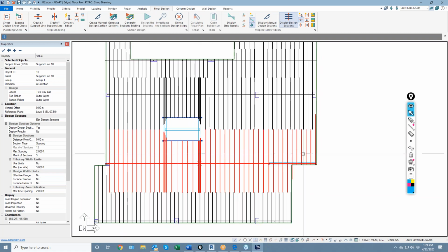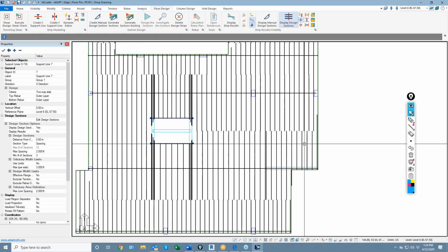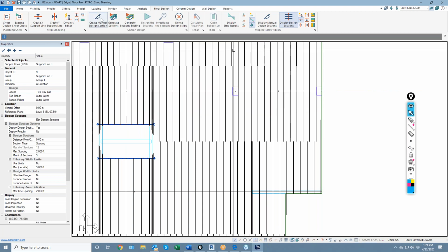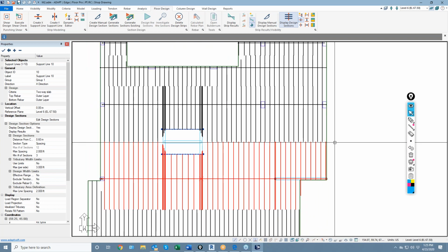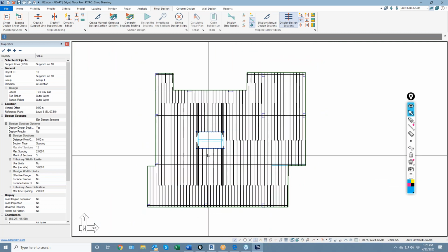So it's not a big issue here, but if we wanted to resolve that and revise it, we could take this over to the edge, and because that point is at the same position as this point, now this doesn't extend over, because this one was previously scooted to the left. Or you could use a splitter there also. So the point locations are important to note, to determine how they might be affecting the different section cuts.